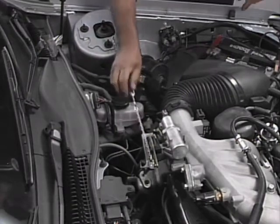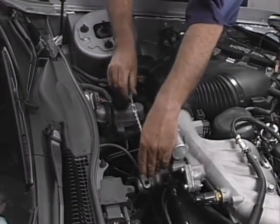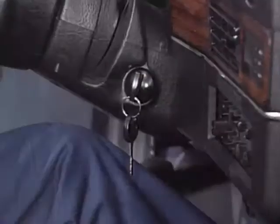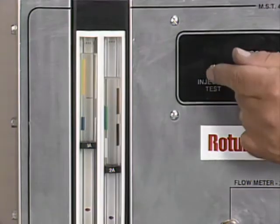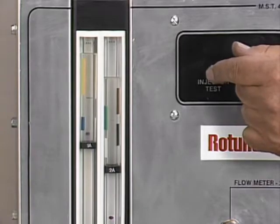Once the engine is warm and the idle is stabilized, set the idle at 2,000 RPM and run the remainder of the 10-minute tester cleaner cycle. At the end of the 10-minute cycle, turn off the engine and discard any of the mixture remaining in the tester tank. Then test the injectors to see how cleaning affected their flow. Flow readings within or slightly above the correct range are okay after cleaning.